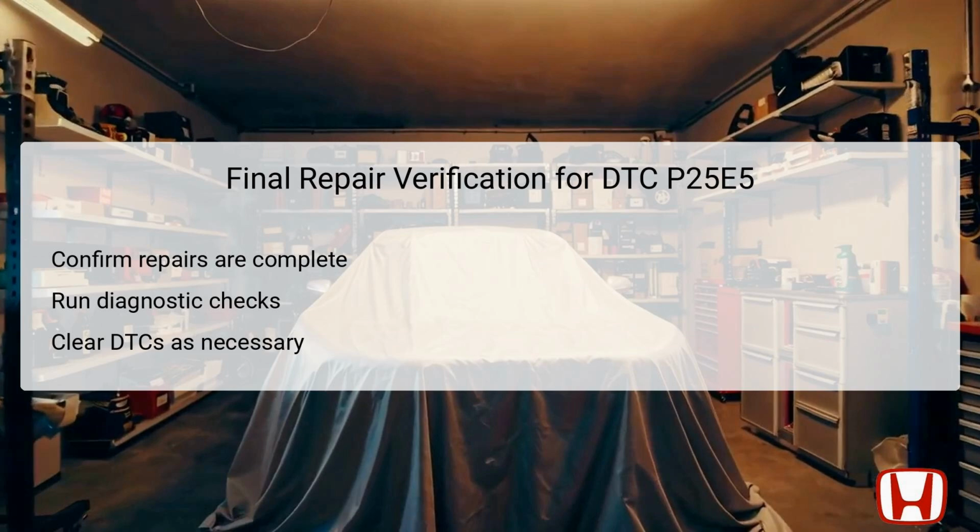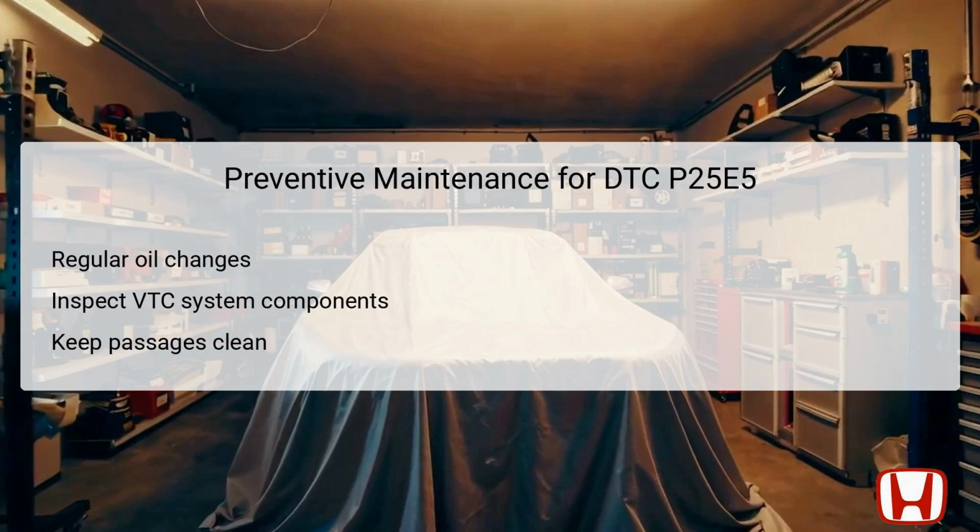If all checked systems appear normal, it is prudent to clear any stored diagnostic trouble codes from the PCM to reset the monitoring system. This step will enable the vehicle's computer to create a new baseline for performance. Finally, run a short test drive again to confirm that the previously identified symptoms have been rectified and that the DTC does not reappear. To avoid future occurrences of DTC P25E5 and maintain optimal engine performance, implementing a solid preventive maintenance routine is highly recommended.